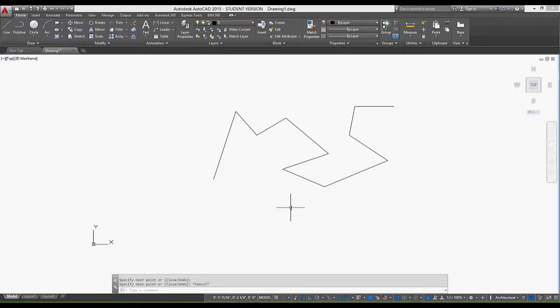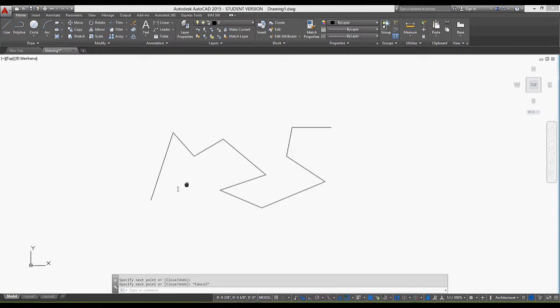Now we'll repeat this, practicing the tools with polyline, rectangle, and circle, placing random shapes within the model space. Polylines consist of individual segments that can be lines and arcs, and then they act as a single object. Now, when we get into some of the modifiers, we'll specifically note the difference between the line and the polyline.